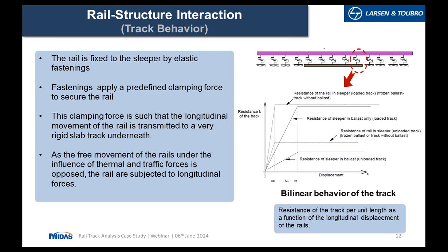It also gives us somewhat of a flexibility to design the forces according to the structure that we have. If we reduce the toe load of the fastenings, we can also reduce the stresses that are occurring in the rails. And this is one of the very strong tools that is provided to railway engineers to manipulate the stresses that are generated.